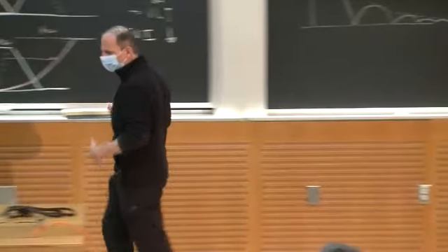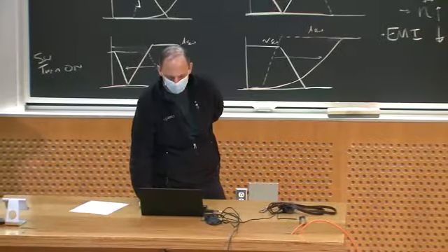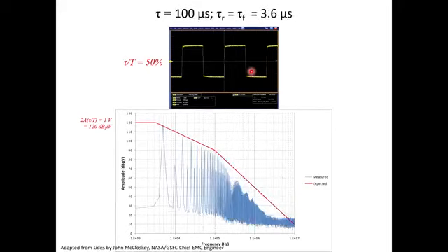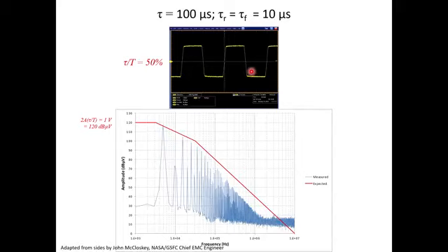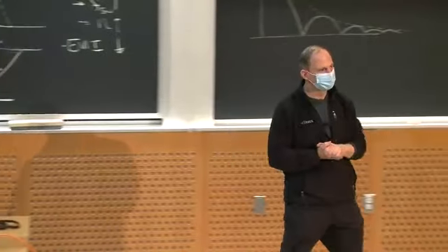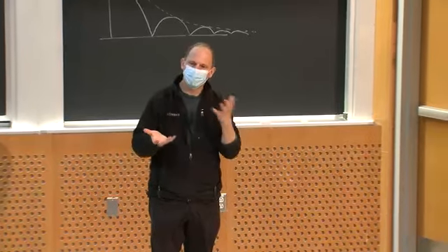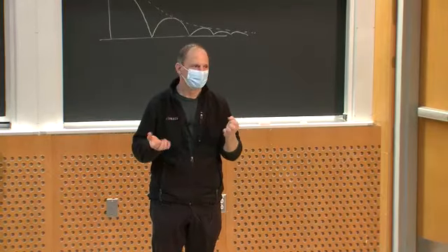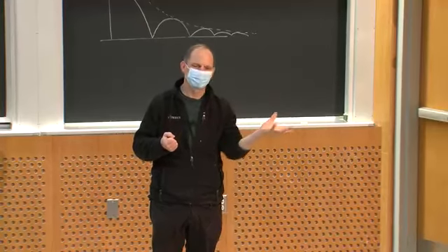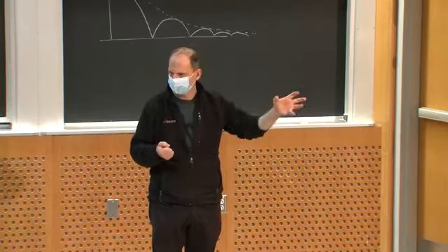So one of the effects you get is, as you slow the slew rates, you start to kill off a bunch of high frequency content, okay? Now, your filter is typically sized for the lowest frequencies, right? But when you put parasitics in there, remember that we saw the circuit parasitics make the filter start to drop out its capabilities at high frequency.